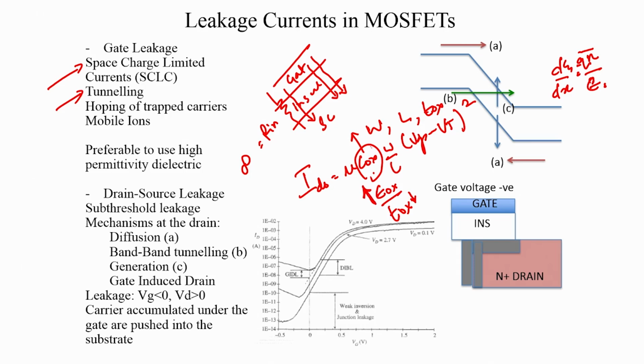And in this way we can still improve your field effect and at the same time not give in to all these gate leakage mechanisms. Now, the gate leakage mechanisms effectively reduce the input impedance. They do not keep the input impedance infinite, and they make it quite finite. Okay. And this has got implications when we design circuits.